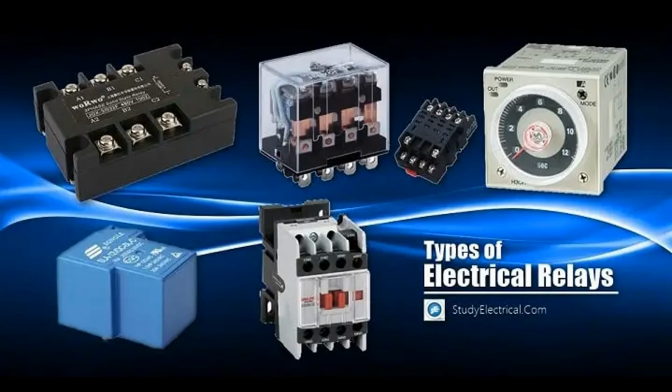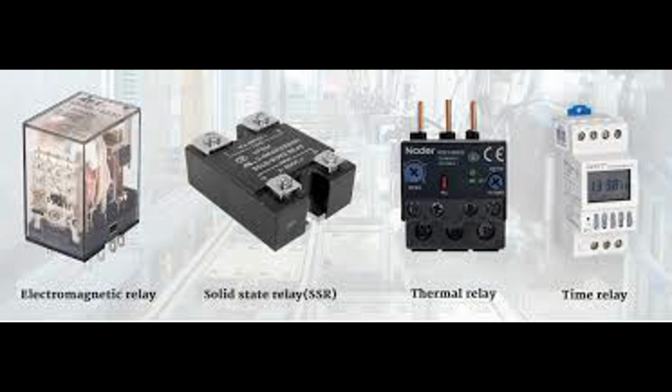Structure and components. Coil: similar to electromagnetic relays, the coil generates a magnetic field when energized. Timing circuit: this component controls the delay period. It can be implemented using mechanical timers, capacitors, resistors, or digital circuits in more advanced relays. Contacts: the switchable components, normally open or normally closed, that change state based on the timing circuit's operation. Adjustment mechanism: many time delay relays have a knob or digital display to set the desired time delay.